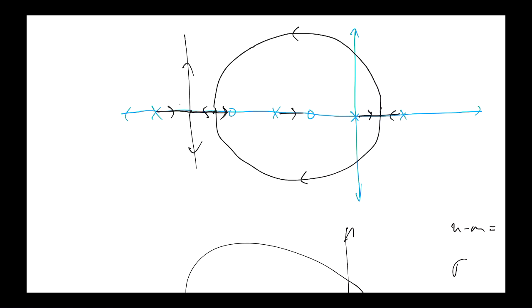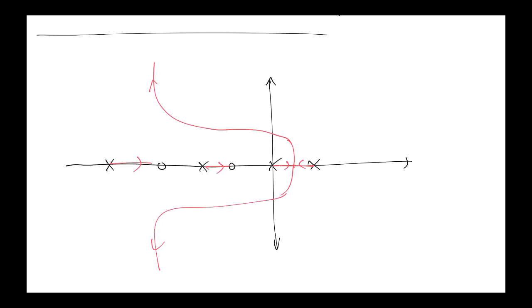Okay, so don't get hung up always on the details of, but I went away in MATLAB and I typed this in, I didn't get this, I got this. If you interpret it in the right way, they are the same thing. For high gain, we get the same outcome. And to get the outcome that we want, we have to have high gain, because the outcome was about trying to make sure we had very good damping. With the closed loop poles here and here, we're getting good damping because the real part in magnitude is much larger than the imaginary part, and that's what good damping corresponds to.